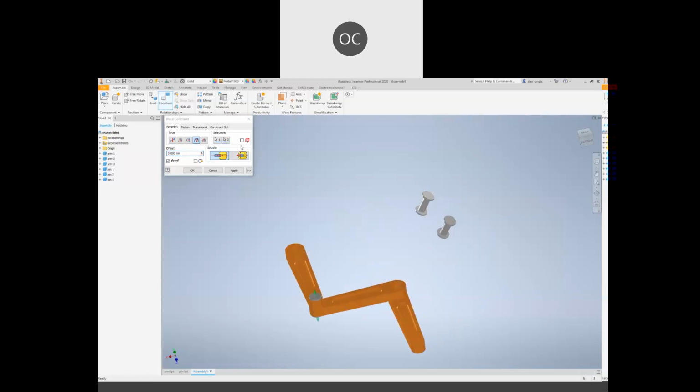Show to you again. Assembly, change to insert. So you go to your pin, it's on downwards. Click on it. Go to your host, ensure it's moving upwards, the opposite of the pin, then you click. So you will see everything will be nicely fit.